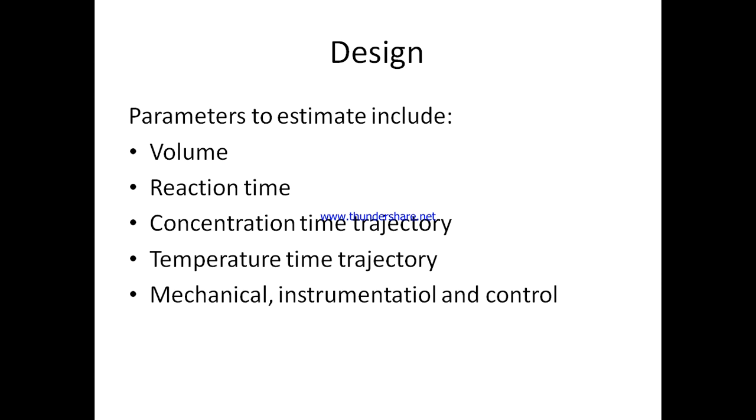Although in using batch reactor, reaction time is just one of the time parameters that is needed. We have time for charging, we have time to raise the temperature of the reactant to the temperature that reaction will take place. We have time for cooling. We also have time for discharging, cleaning of the reactor. But reaction time becomes a very important parameter to estimate for a batch reactor. Okay, so we also do that in detail subsequently.